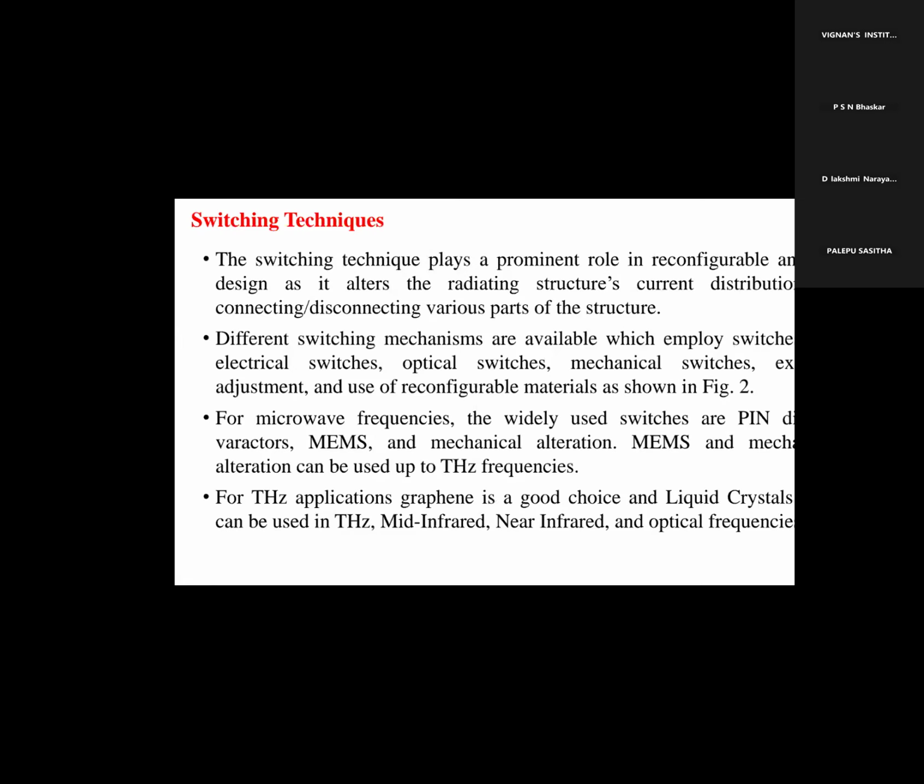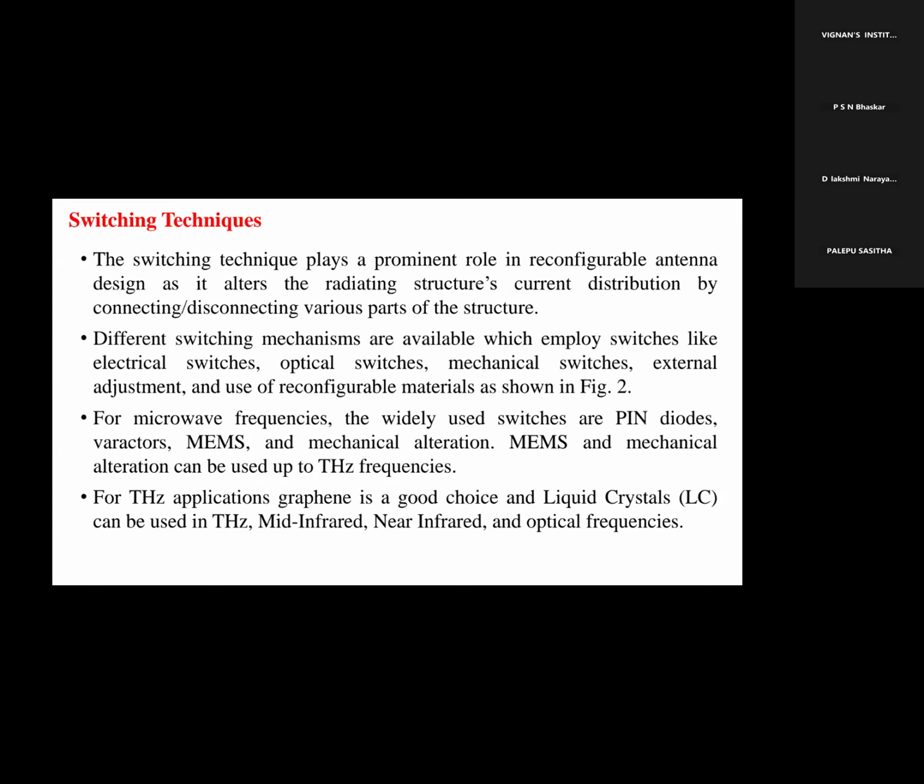Now we will discuss switching techniques. Switching techniques play a prominent role in reconfigurable antenna design, as they alter the radiating structure's current distribution by connecting and disconnecting various parts of the structure. Different switching mechanisms are available, which employ switches like electrical switches, optical switches, mechanical switches, external adjustments, and use of reconfigurable material, as shown in the figure.